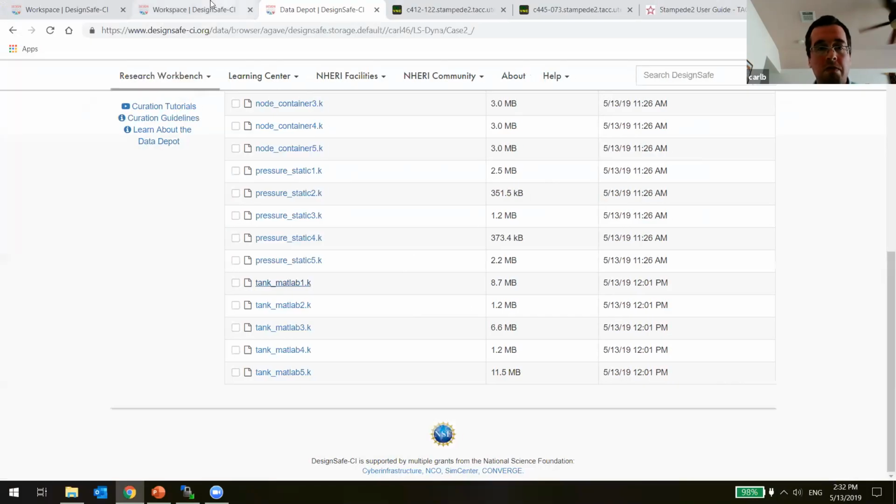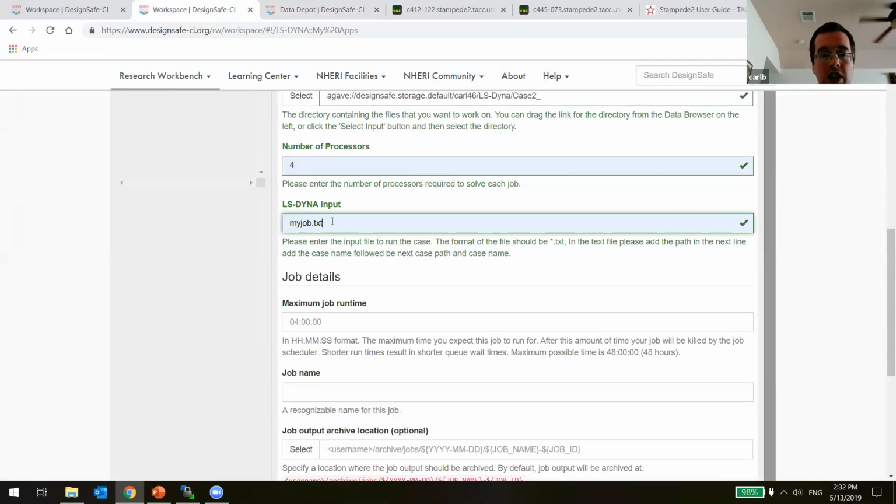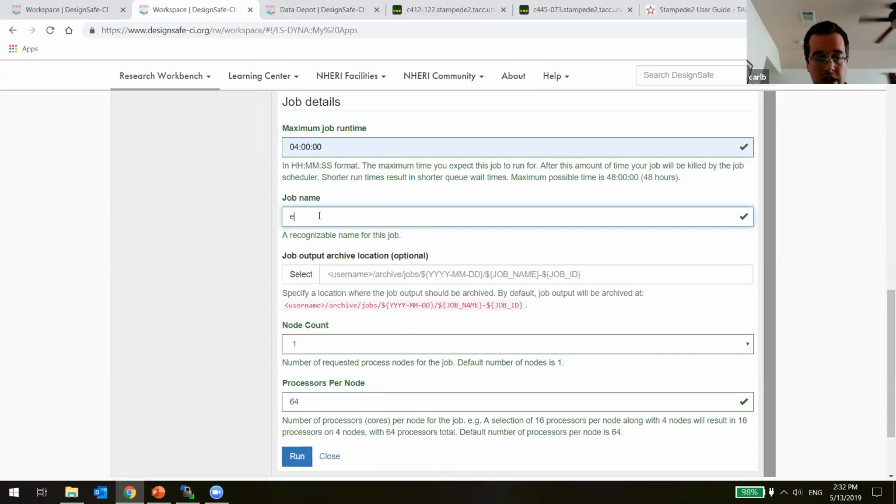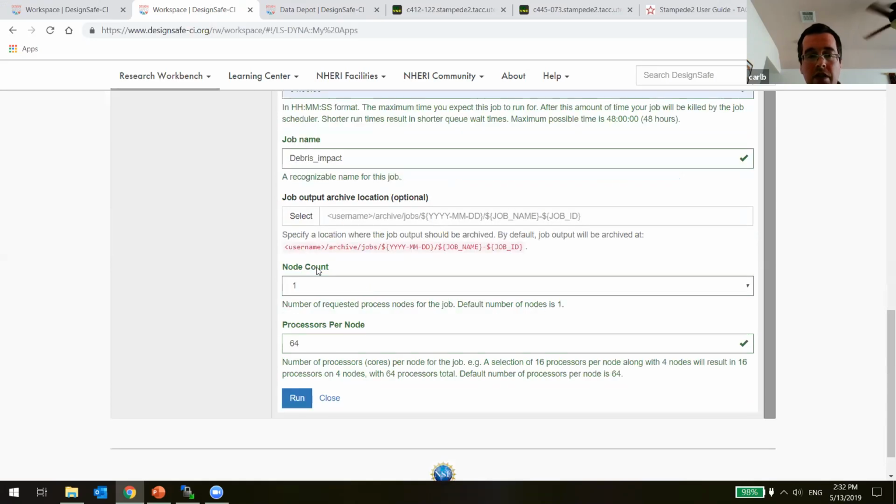So now we're going to go back to the workspace. So I selected my job.txt. So again, this has a list of the 5 different jobs I want to run. We're going to select the job runtime. I'm going to ask for 4 hours, and we're going to call it debris impact. And the output, you can leave it as the default location. Then you have to select the number of node and the number of processor.